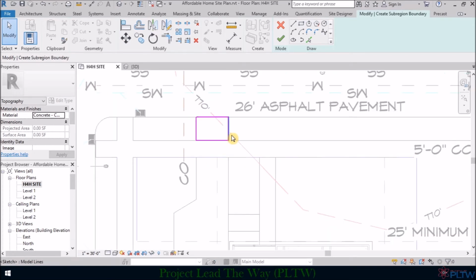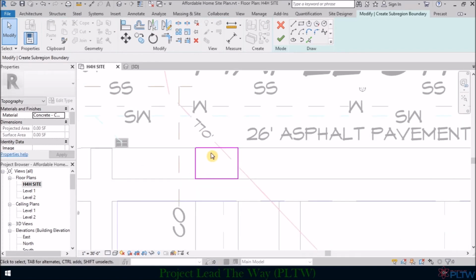Now at driveways or aprons that connect to a road, there is usually a radius here or a diagonal that allows a person to make the turn into and out of this driveway. I like the radius. I think the radius looks better. But the reason why you want to do that is not just to make the turning into and the turning out of the driveway easy, but you want to make sure that over time that someone doesn't drive over this corner of the driveway and the edge of the road.